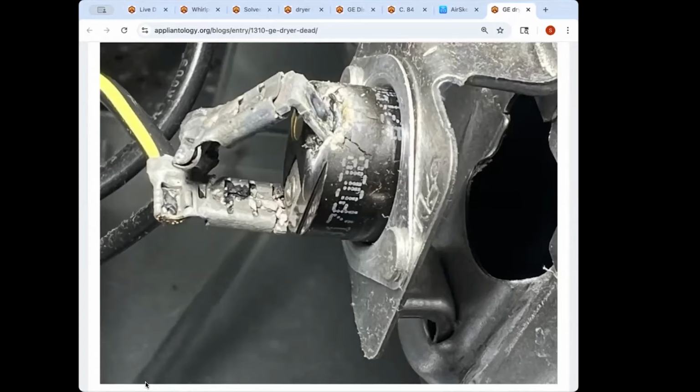I had troubles with a Bosch dryer one time, and I took it apart and couldn't figure out anything, and it ended up being the lint trap, with fine lint. Yeah, that'll affect airflow. Frigidaire has a service bulletin. They changed out the lint screen on one of their dryers because it was so fine that it was not drafting the air through it and it was causing problems.